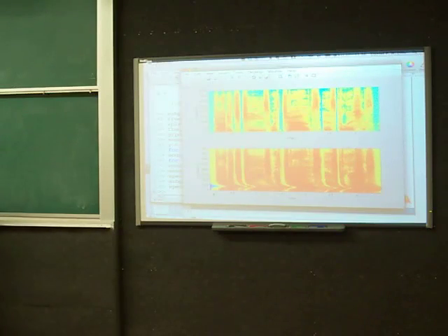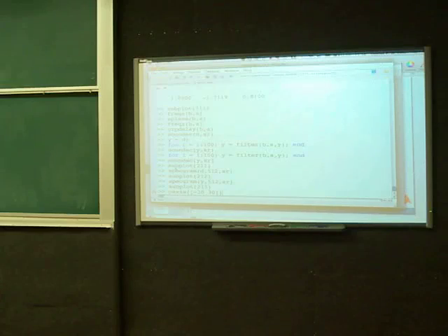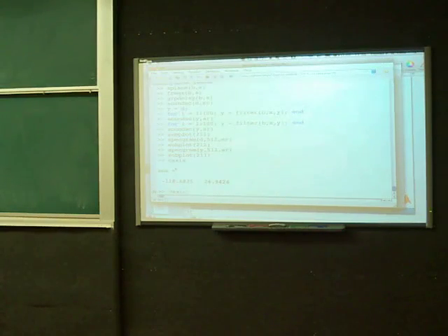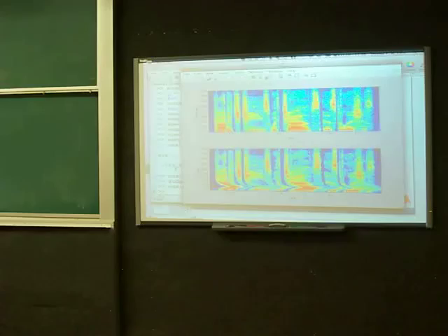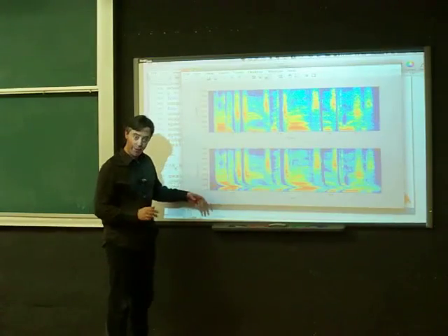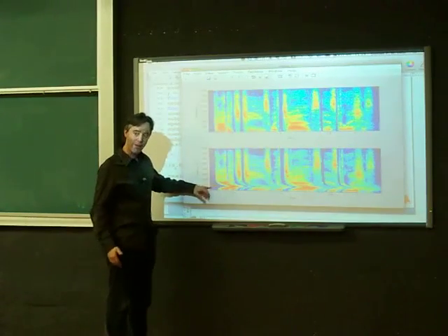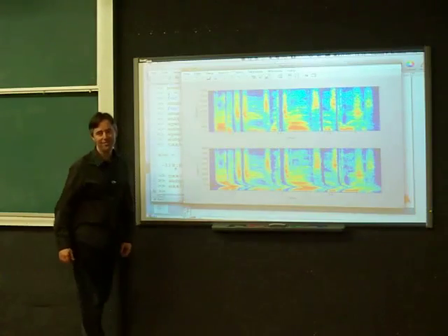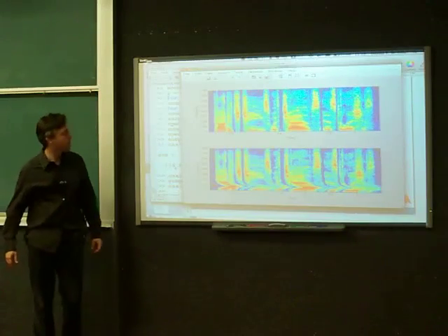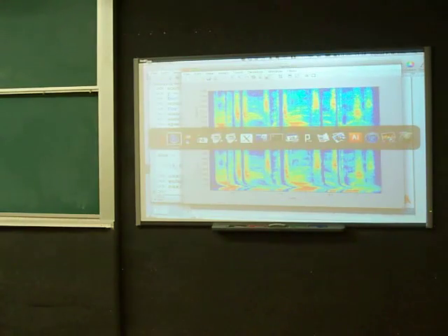It does, but that's just the color axis in MATLAB, right? So if I subplot 2 on 1, look at the color axis here, and then maybe set it to something like minus 60 to 20, and then subplot 2 on 2 and give it the same color axis, then they look the same, right? MATLAB does this auto scaling of the color axis because we pulled in this hole here. It was pulling energy when there wasn't, from before when it's 0. It has a much lower minimum, and so when it auto scales, it just pushes the scale up. Because, of course, the all-pass filter does not change the total amount of energy. It just moves it around in time.